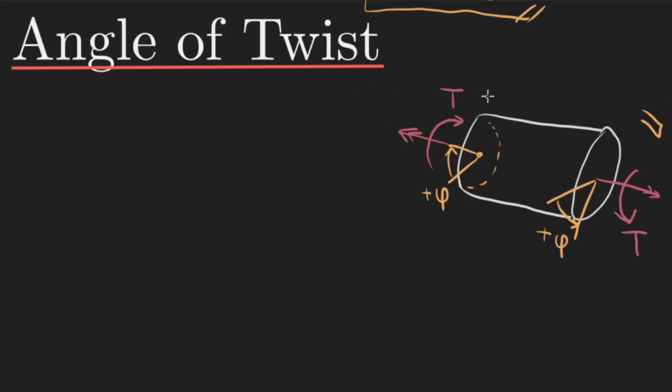And then for this way, you'd have your thumb pointing this way, and then your fingers would kind of curl in this direction like that, which is where we get the torque in this direction from. And then for phi's, which are our angles of twist, it's going to be the same thing. This is the positive direction, and this right here is the positive direction on this side.